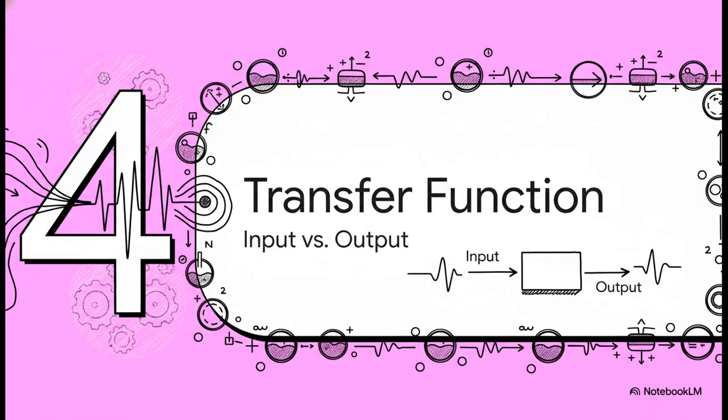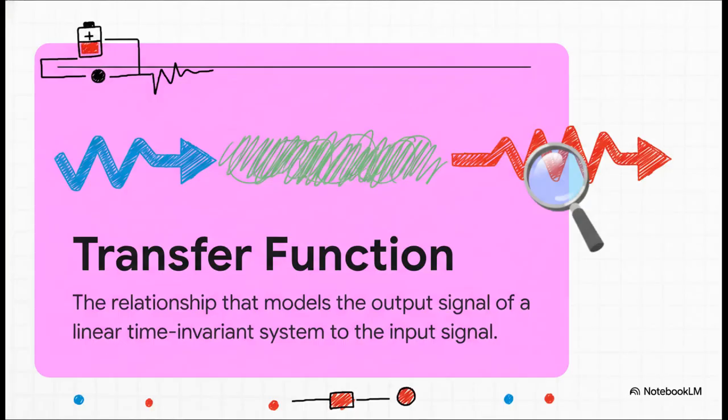Okay, we've got this great visual tool now, but let's zoom out for a second and think about what impedance really is. It's not just some property. It's a description of how your system behaves. It's what engineers call a transfer function. Now, transfer function sounds way more complicated than it is, I promise. All it means is you put a signal in, your system does something to it, and it spits a different signal out. The transfer function just describes what happened in the middle.